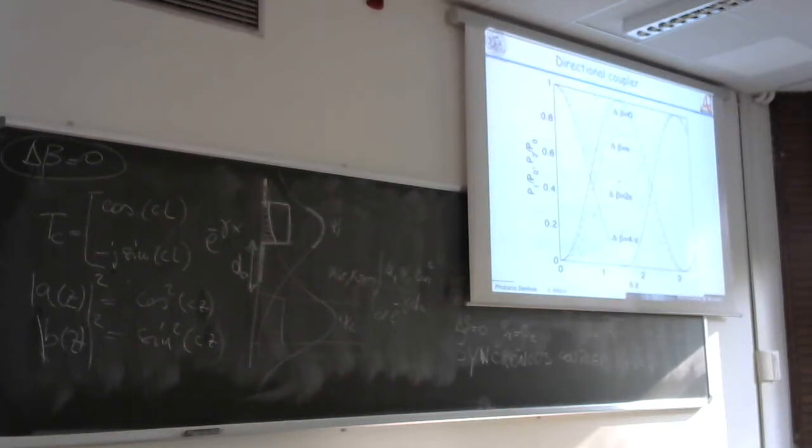The phase shift is some coefficient of your K. The phase difference between the two outputs is related to your coupling ratio, only for the asynchronous case. I don't give you the expression of the phase, it's not really very important. But for a synchronous case, the phase shift is half pi.